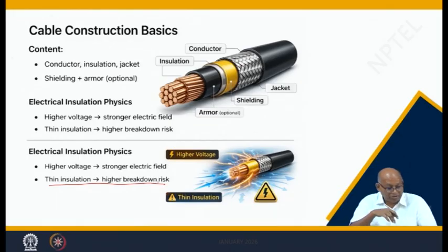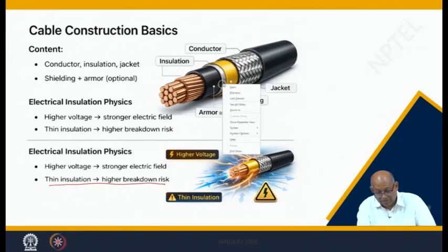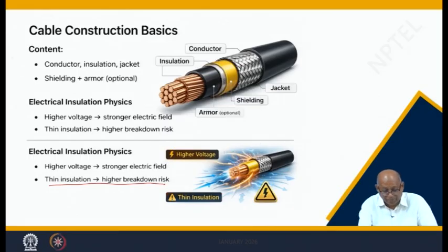So, this is the cable construction. If there is a question on this, you should be able to give a complete layout and explain why each part is there. For example, why there is an external conductor here, it is further shielding. There is another conductor, this conductor is shielding also, and prevents moisture from entering. Then there is armor again, why it is there, and all these jackets, you should be able to explain.